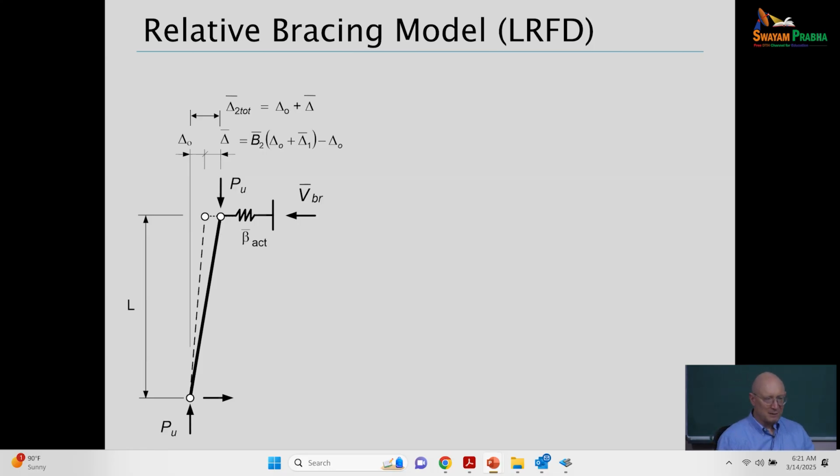Or if I've got a discrete grounded brace to the top, the way I'm showing it here, either way it's a stiffness delivered or a flexibility of a spring bracing the top of the column. So the derivation's the same. We'll call it a relative brace, but the nodal brace would be the same thing here.